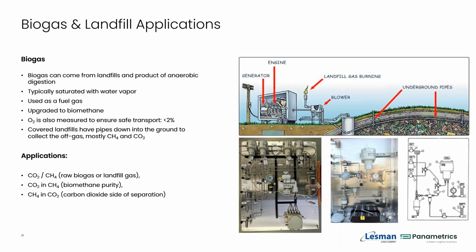Everything is going to be of the right materials, typically stainless steel, but we can even go to materials such as Hastelloy. The thermistors that are in there are glass sealed, so typically, again, not an issue with corrosive gases like hydrogen sulfide. Even carbon dioxide can be a corrosive gas in that you can get carbonic acid if you have enough moisture and oxygen. So no, these are very simple applications for the transmitter. The small amounts of H2S that might be there are not a problem.